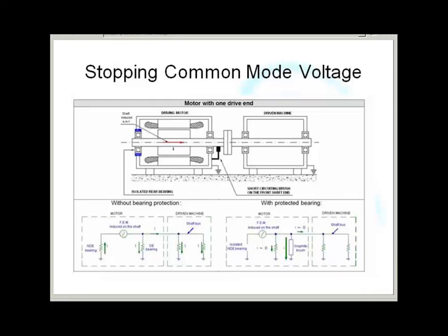So, that's one way of stopping a motor overheating, using space vector modulation. According to the manufacturer's literature, and I've got reason to believe this, with space vector modulation, you can start a motor up and run a motor all day at 1 hertz, full torque.